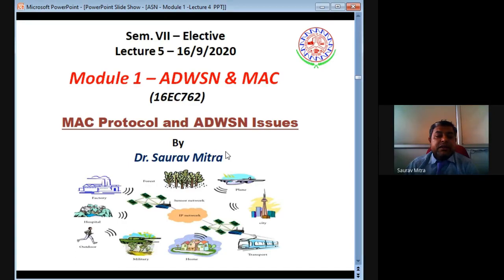Now as we increase the number of sensor nodes, the bandwidth is reduced for each sensor node. So what is bandwidth actually? Bandwidth is a kind of information capacity of a node. If bandwidth is more for any node, that node can carry more information from one place to another, so connectivity becomes better if each node has a wider bandwidth.